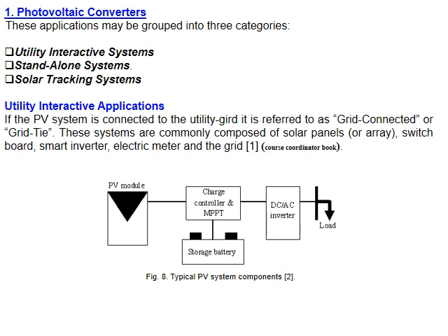We mentioned that the solar panels or modules could be used for utility, connected to the grid, standalone, or in a tracking system, okay? Now, utility is very simple. We have the array here, a PV module or array, or let me say plant, connected to a charge controller to control the output voltage and current coming from the cell. If it is connected to the grid, then definitely we have an inverter to convert the DC part here into the AC part here and give it to the grid or to the load. Sometimes they use batteries for critical load.